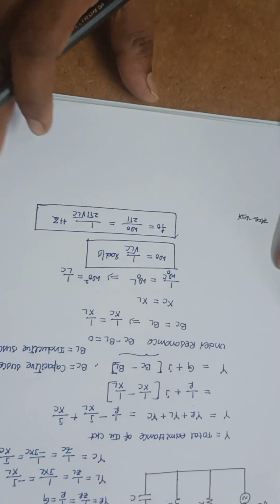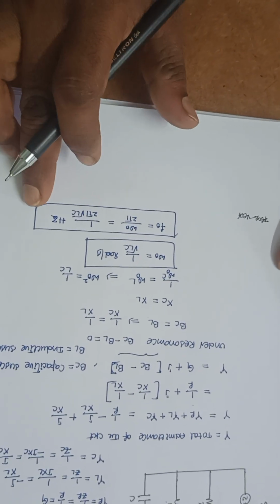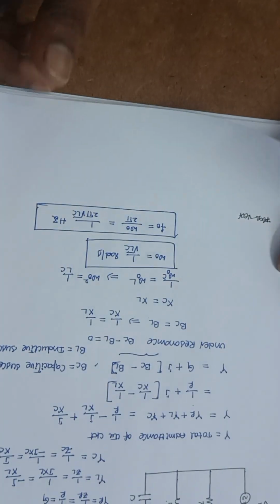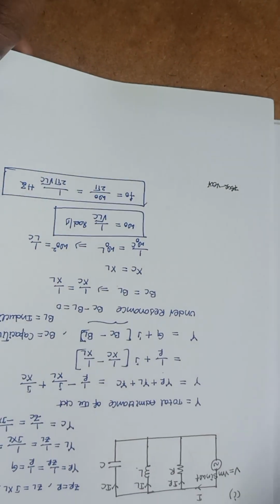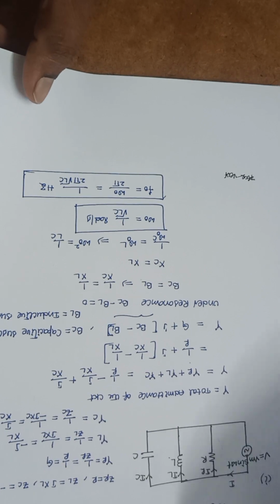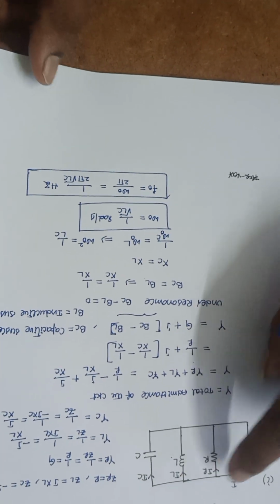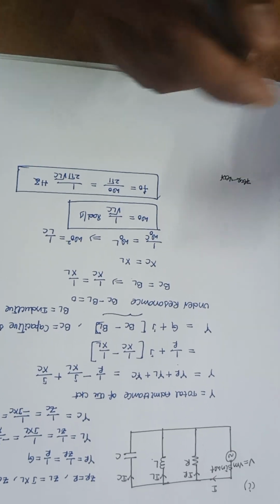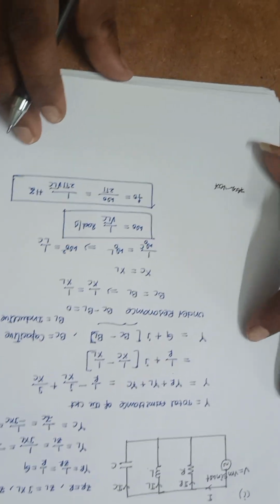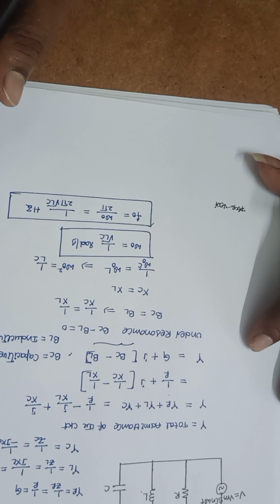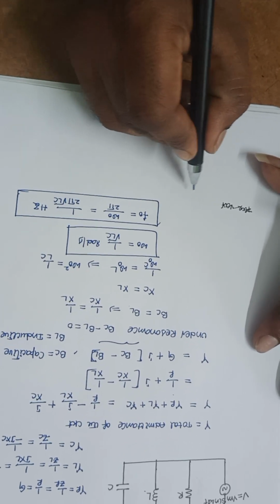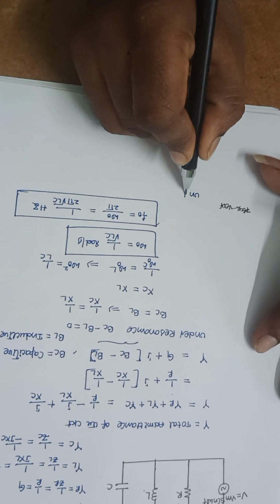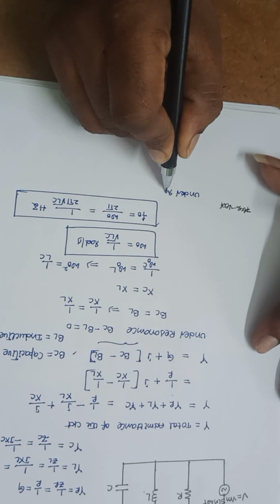So you will remember up to here F naught is equal to 1 by 2 pi root LC hertz for a parallel RLC circuit. Next thing here, quality factor. So F naught and quality factor. Before going to find this quality factor, first let me draw some of the concepts, that is, some of the conclusions under resonance condition.